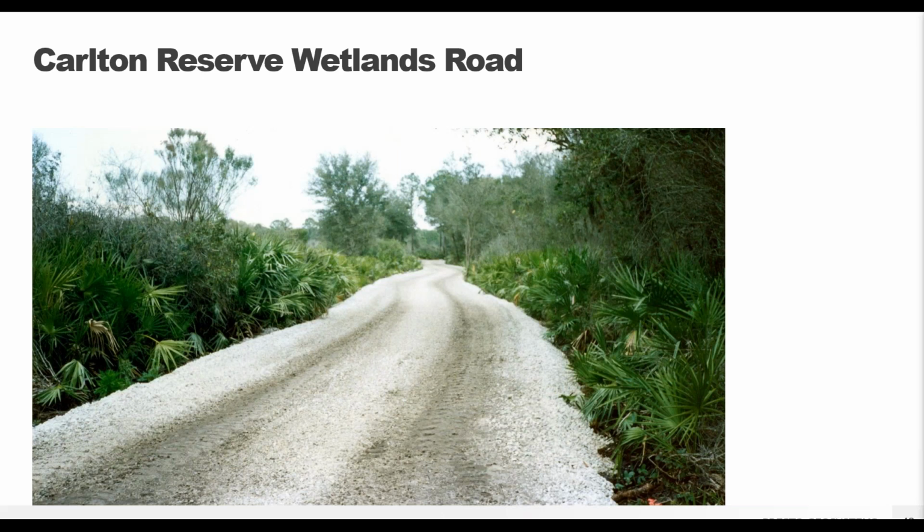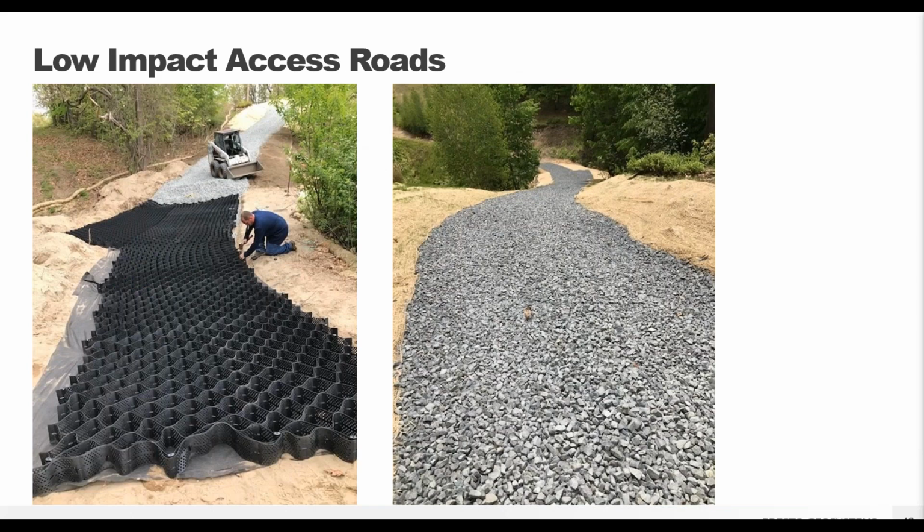So the GeoWeb panels are both strong and stable, and that's a very important feature when you're trying to reduce your overall impact to the areas around you. By being able to reduce your cross section, less excavation is needed, so there's less disturbance to the installation process. By reducing the overall lifetime maintenance, there's less chance for vehicle encroachment on the vegetation around your roadway. A washed or clear stone, so where you have that really minimal fines content, is used to create those stable, permeable, low impact development access roads.